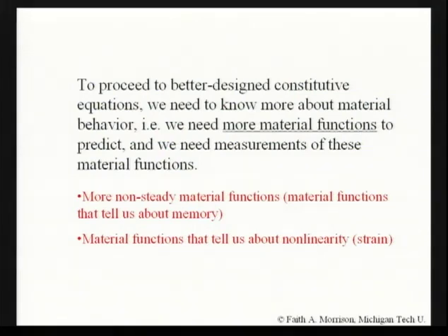So there's our takeaway lesson for today. To proceed to better constitutive equations, we need to know more about material behavior. We need to know more about time dependence. So we're going to discuss next more and different ways of shearing a polymer. It's still always shear flow, but how do we move that top plate? We've gone from 0 to something, something to 0.